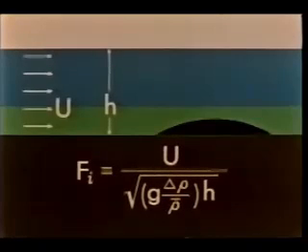A long obstacle and a low value of the internal fluid number of the approach flow leads to subcritical flow at every section and a slight drawdown of the interface over the barrier. This long, gently shaped barrier minimizes vertical accelerations of the fluid, and the pressure remains nearly hydrostatic. That is, the pressure is related directly to the depth.